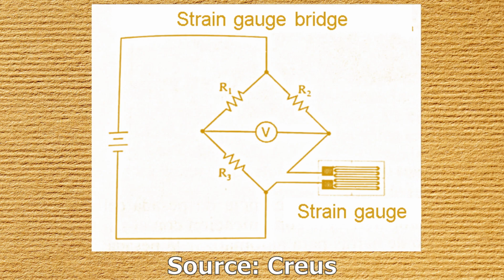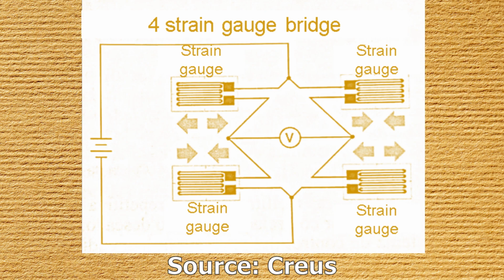Signal conditioners are used, and they are Wheatstone bridges that pick up small changes in resistance and compensate for the effects of temperature. Here we can see an elementary circuit that has the disadvantage of the variable resistance of the connection wires from the gauge to the bridge. A complete circuit with 4 gauges, one on each arm of the bridge, for higher sensitivity. Here, a load of 453 kilograms or 1,000 pounds unbalances the bridge at 15 millivolts per volt of excitation.